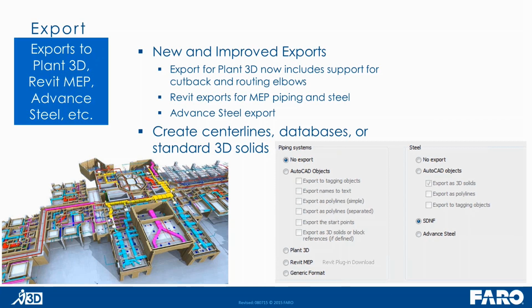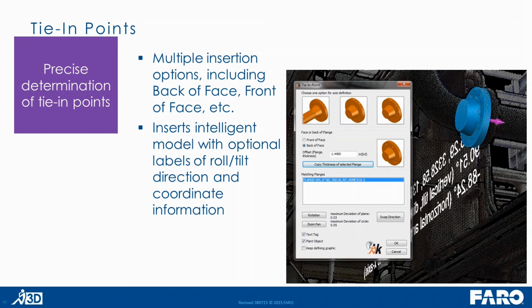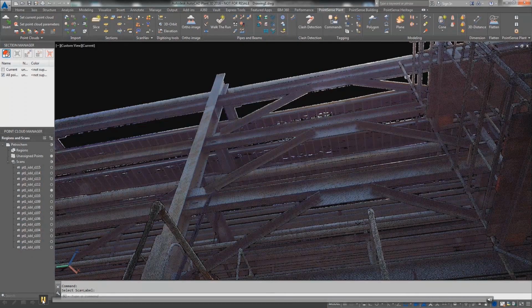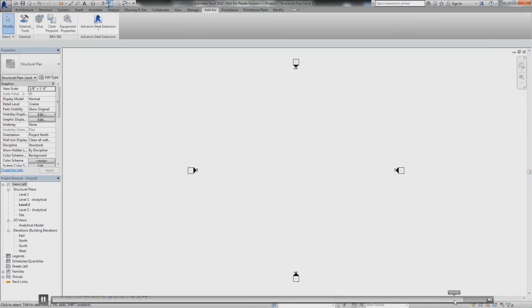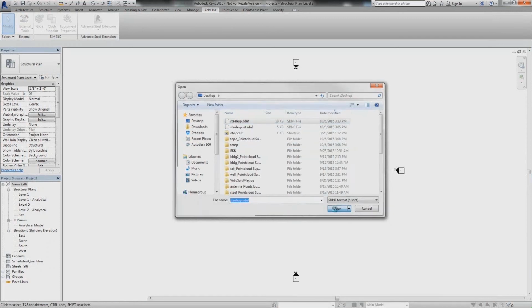Now if you jump into the video and show where you're importing the structural to Revit. Sorry, I'm making you fly around the PowerPoint here. Almost there. Okay. So if you look up here at the top of the ribbon, you see add-ins. It's highlighted now. Then you see PointSense, and next to that you see PointSense Plant.